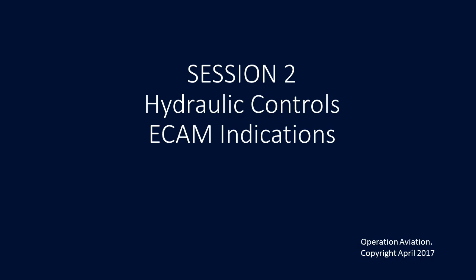We also have PTU status, your power transfer unit indication. That one is located between your green and yellow systems. Green arrows pointing away from the PTU, in white, indicate that the PTU push button is in the auto position and the PTU is armed, but it's not yet supplying pressure to either system. So it's just ready to go, but it's not actually allowing that flow of pressure to the systems. Your normal indication is with both engine pumps operating and the PTU not inhibited.